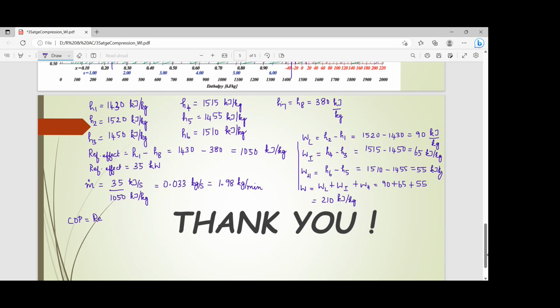So the COP is the refrigeration effect divided by the total work. So this over here is 1050 and the net work is 210. So 1050 divided by 210 is 5. So that is the COP of the vapor compression refrigeration system when I use 3 water intercoolers.